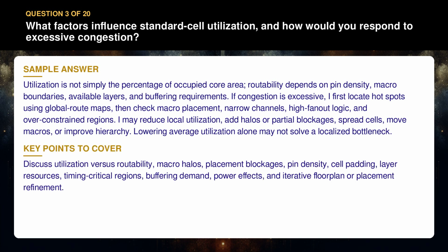Discuss utilization versus routability, macro halos, placement blockages, pin density, cell padding, layer resources, timing critical regions, buffering demand, power effects, and iterative floor plan or placement refinement.